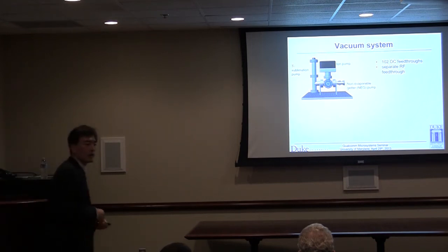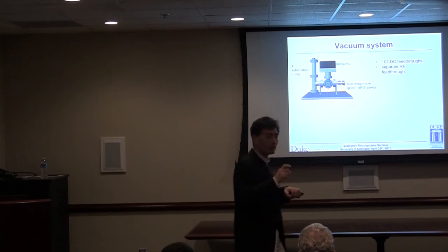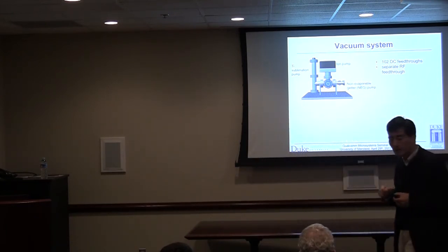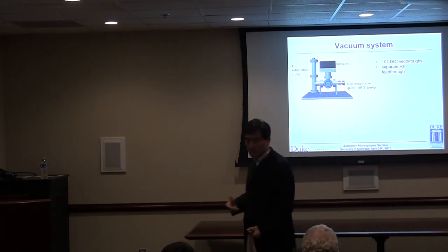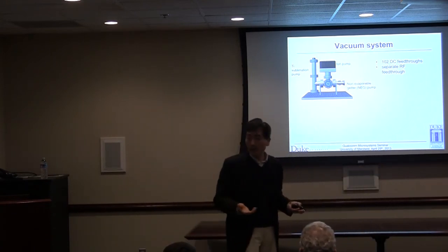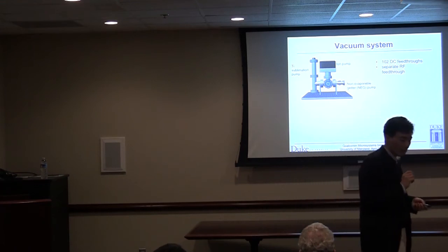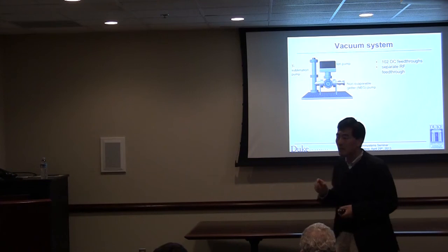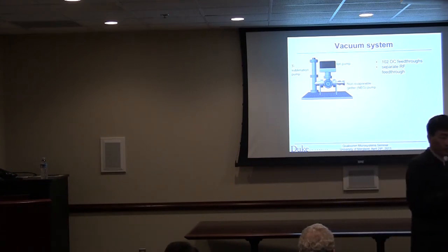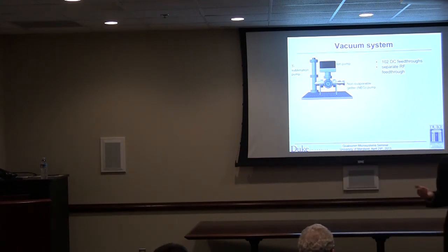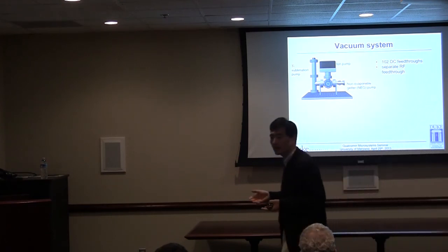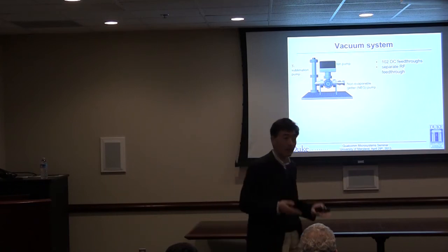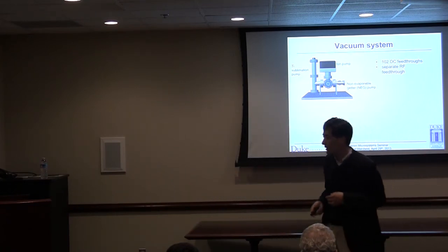If you think about traditional circuits, you take these macroscopic pieces and wire and solder them down onto a PCB, you can do it in your lab, and they work because these things are big, right? But when you try to make these circuit elements in a microfabrication facility, because the features are so small, a piece of dirt can short them, right? So we had to invent clean room technology to make microfabricated circuits work reliably. If you do that, they're very reliable. Okay? But same thing here.